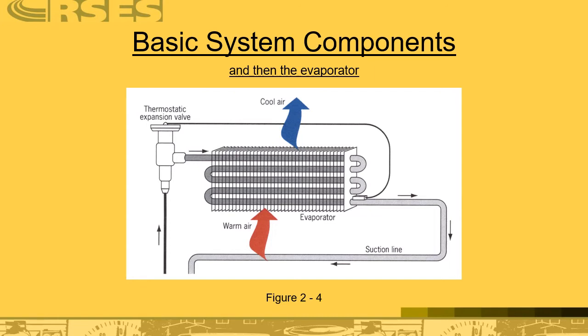you have the evaporator section here, and notice that we're utilizing for our pressure drop the metering device. This is a solid column of liquid entering the thermal expansion valve. The refrigerant enters the evaporator coil as a mixture of liquid and vapor, 75 to 25% ratio, I believe the previous slide talked about.